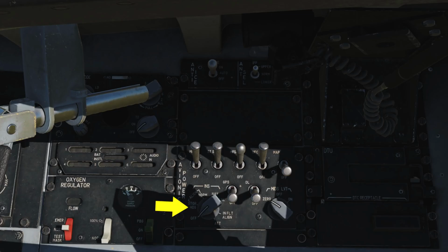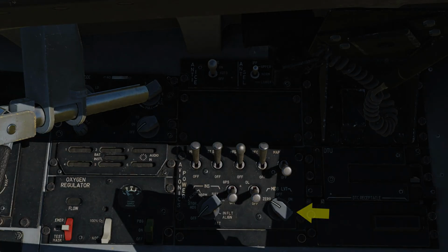And then we have the inertial navigation system knob, or INS, and this has selections for both stored and normal alignment, normal INS navigation, in-flight alignment, and an attitude alignment that allows you to fly along a set course and then have the GPS update the INS. And then last we have the multifunctional information distribution system, or MIDS, that allows you to turn the data link